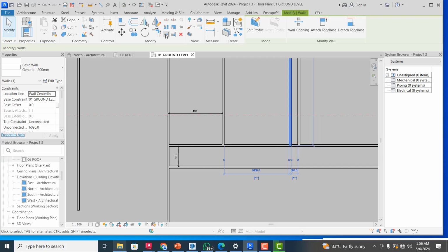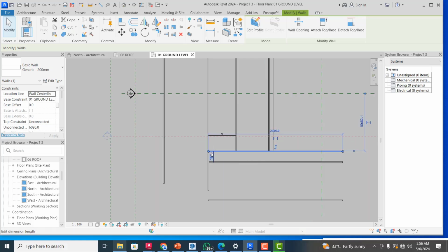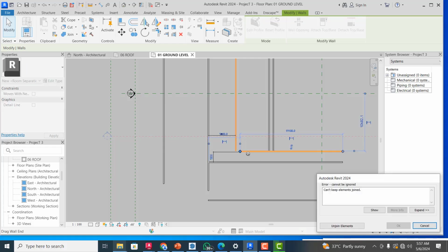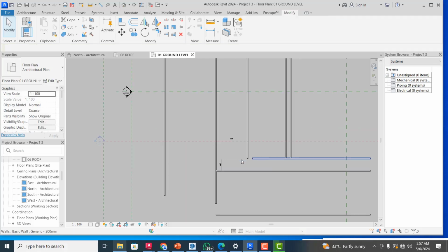And then to do my trim extend rather, all I need to do now is, let's say I bring this back to this point here, or let me unjoin. Let me just unjoin this. All right, so let's say I want to extend this to this instead of this. All I can do now is just to click on my extend, and I'll specify where I want to extend this to. You can see I can just click on this line, and then I will come back here and I'll click on this, and automatically it's going to extend to this particular line.